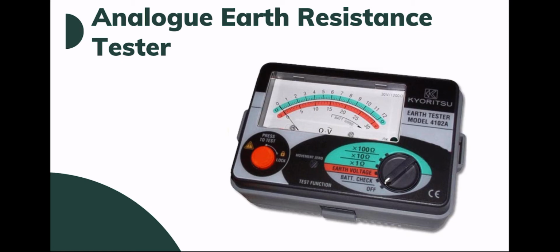There are two types of earth resistance tester, which are analog and digital. The first one we want to tell you about is the analog. The analog grounding resistance tester is realized by four main blocks: DC generator, rectifier, current and potential coil. The deflection of the pointer of the analog screen depends on the ratio of the voltage of the pressure coil to the current of the current coil.